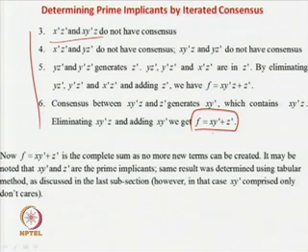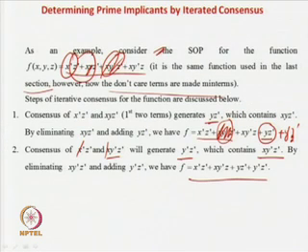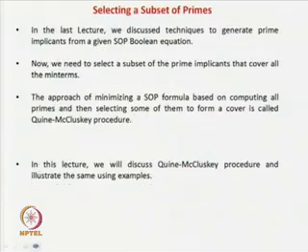In this case, it depends on how large you have written your SOP formula. Generally SOP formulas are written in a small way, and even if they are large, it is somewhat okay. But if you take any SOP formula and go for a canonical representation, then you start off with the full exponential blow up, a very big size of the problem, and then try to get the prime implicants. Here we are trying with a much smaller subset of the problem, and we are not blowing it up, we are directly going to find the prime implicants.